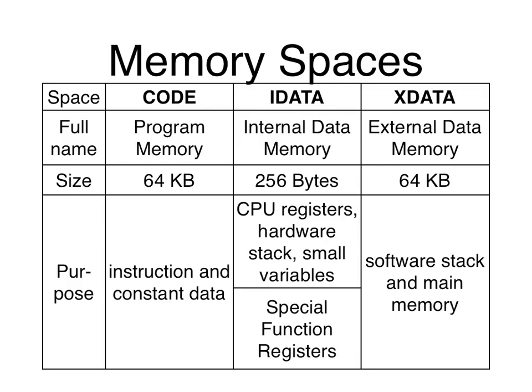The other half, that is 128 bytes of that space, is for special function registers or SFR. And we're going to be talking about SFRs over and over again. So remember, SFR stands for special function register. SFRs are critical to how most microcontrollers work.